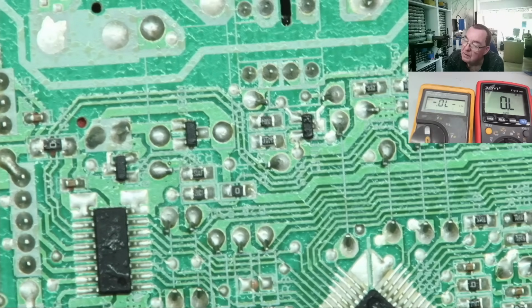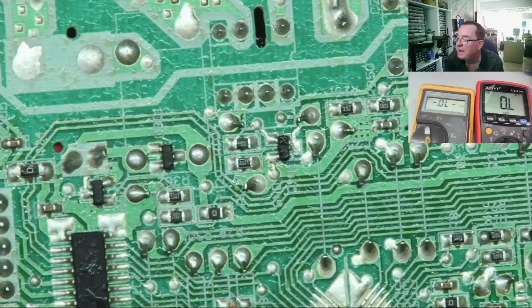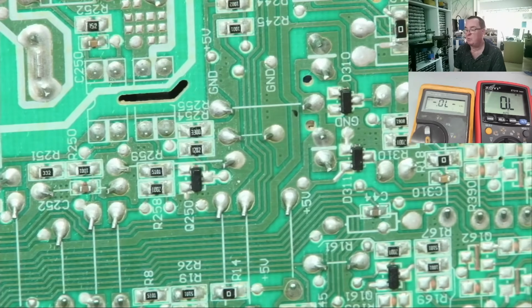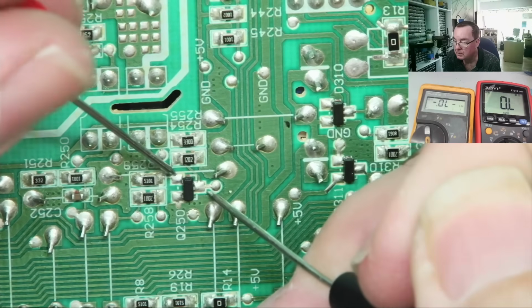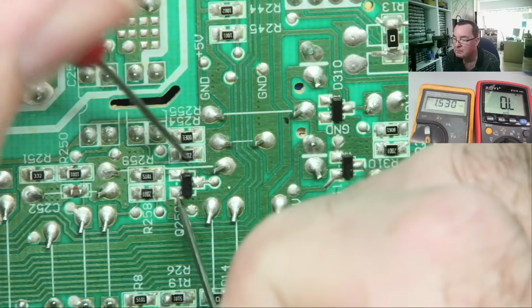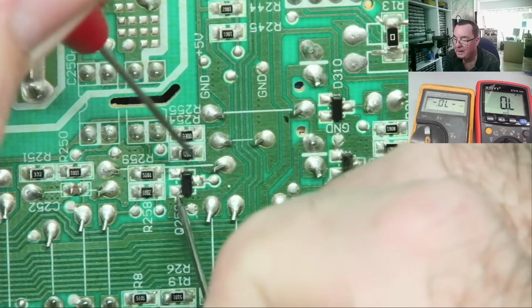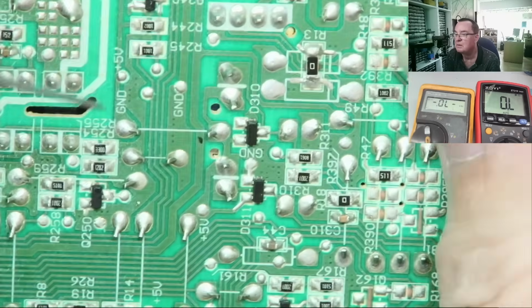If you find multiple devices with the same SMD code, then you'd expect them to basically read the same in circuit. Bearing in mind there may be other things wired across them, of course. So, transistor or MOSFET. Bipolar transistor, NPN by the looks of it. I could test all the other directions, but I know it's not short and it looks like an NPN transistor.